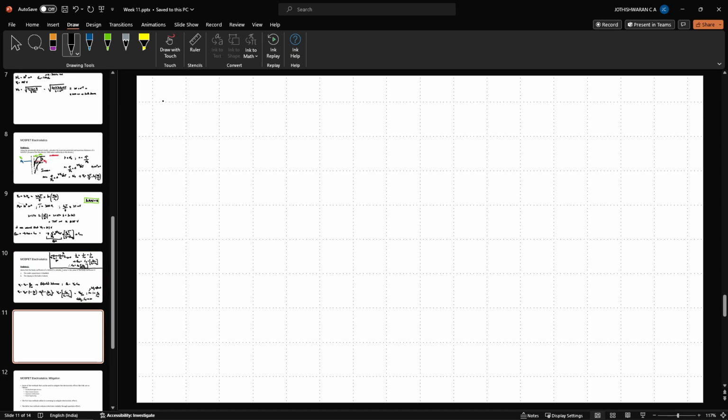So how do I double the oxide capacitance? I can do that by increasing the area, but we don't want that because that will also effectively increase the channel length. I can make the oxide layer thinner, or I can double the dielectric constant, epsilon becomes 2 epsilon. So if we do that, then Cox goes to 2 Cox.